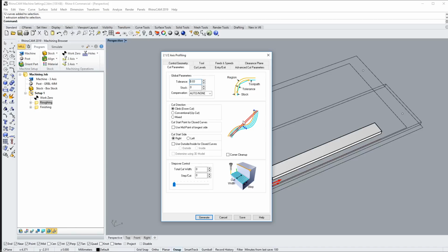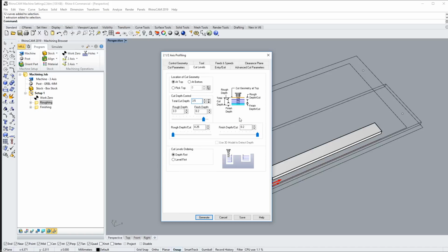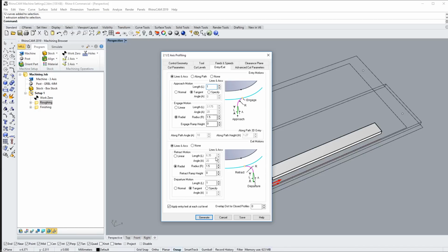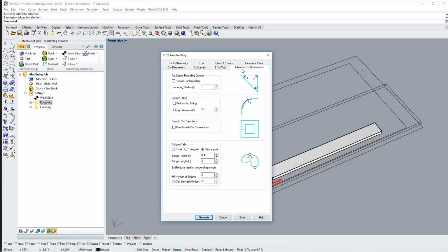It's all over the place, but to be able to switch between those two, there are times when you need to use them. Or hey, you can use both if you want to cut really fast. So then you have your cut levels. This is your depth cuts, but you have really fine control over that, and you have a finishing pass there. You have your entry and exit. So when you want to spiral in and spiral out, to get good, plunging is hard with a bit. With a flat bit, maybe some of these end mills don't even have the center cutting ability, so you cannot plunge.